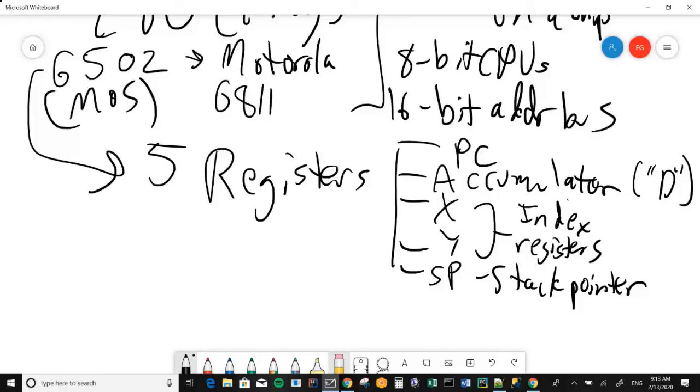Question. Yeah. When you say in hardware, you could tell it how it's going to be animated. Yeah. You mean you're coding it in assembly language or machine language? Oh, yeah. So because it's all memory mapped I/O, you would store values in memory locations that were mapped to the graphics card that would tell it how to move it. So essentially what you're saying is, you're telling the graphics card, I want this sprite with its upper left corner at this X coordinate and this Y coordinate. And it would put it there. And so you'd have data structures in your program tracking how you want it to move, right?